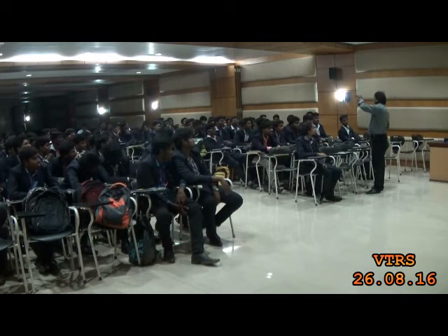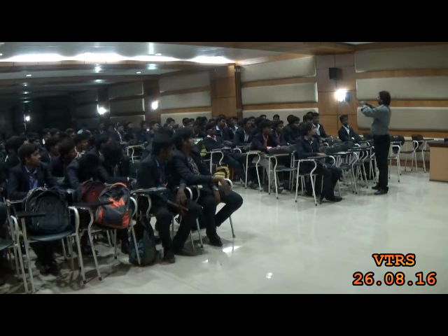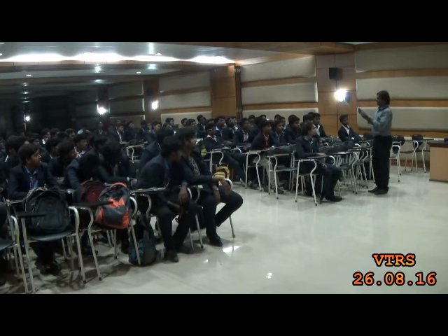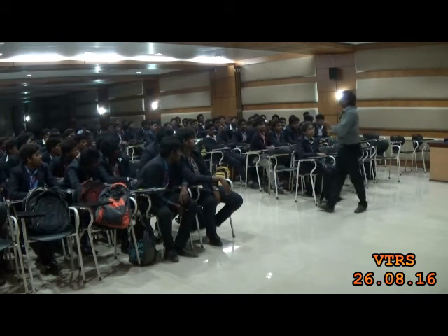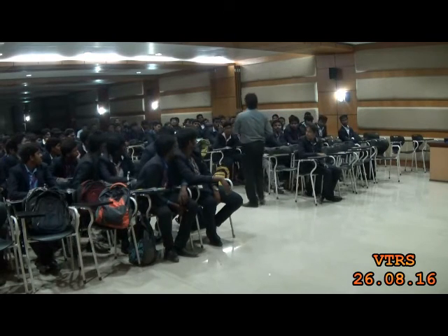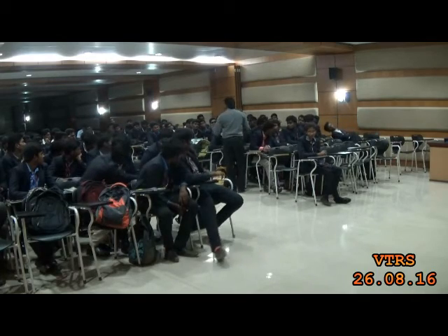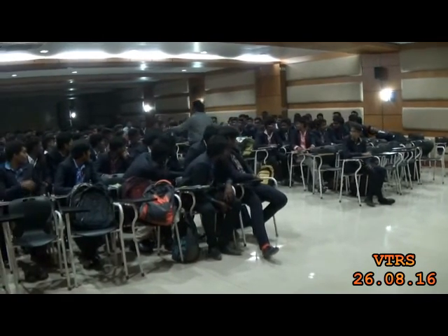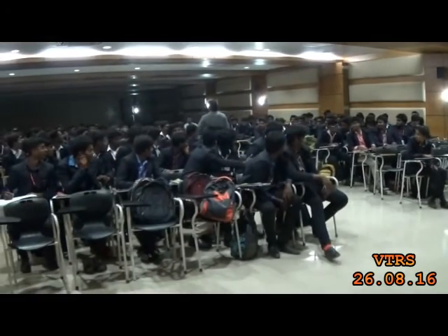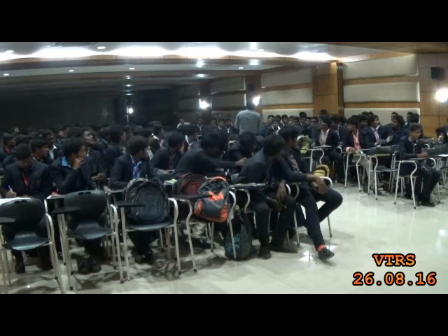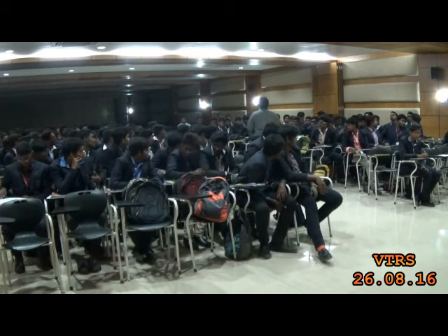See, this is the material. What kind of load am I going to give? It's a tension load. So in tension I have taken this. You can see this one, right? Again, if I keep it there, I am finding the same place. You see how it looks. The fracture is flat, right? It is very flat, like your chalk piece. Do you see any ups and downs?